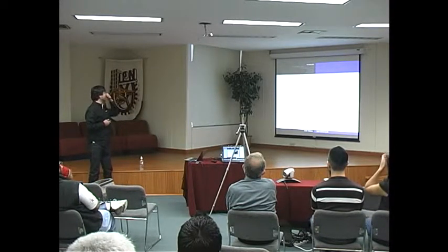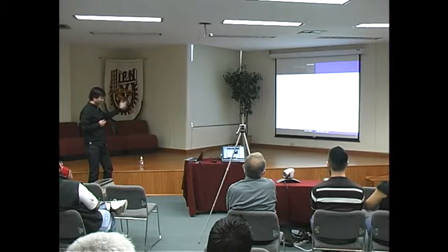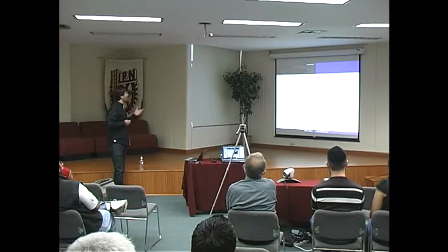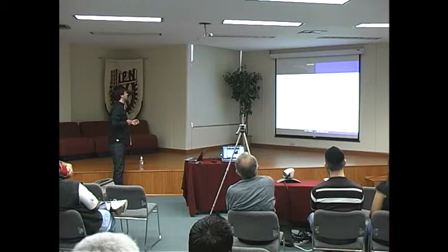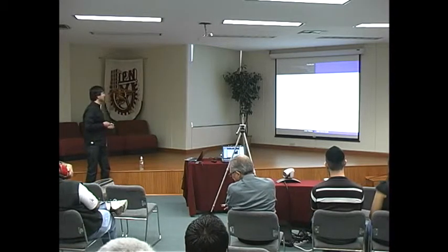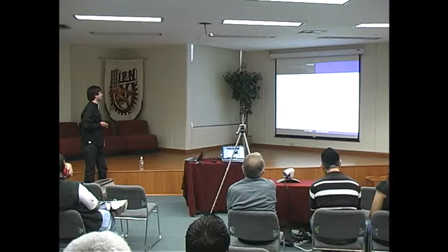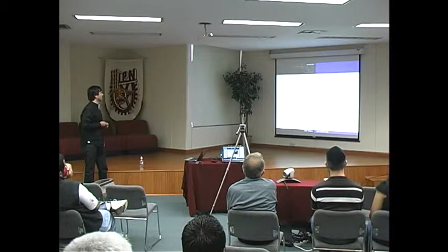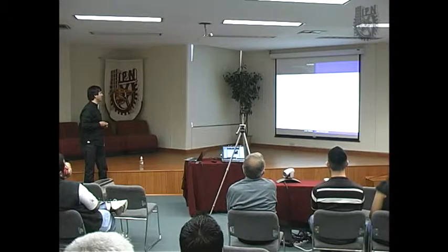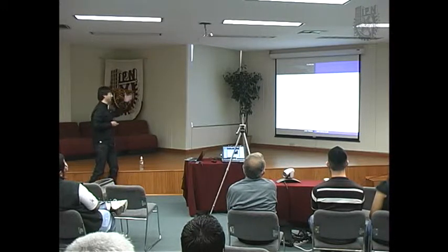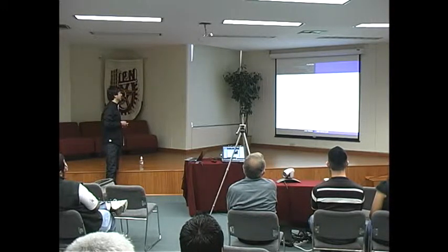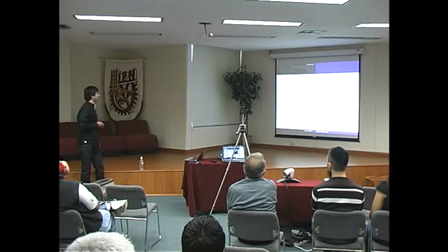The purpose of this slide is to introduce you to the pulse width modulation concept. Here we have a green signal. This green signal is compared with a triangle wave signal. So from the comparison, we have a square signal. This square signal can be used to perform the commutation in the boost power converter.